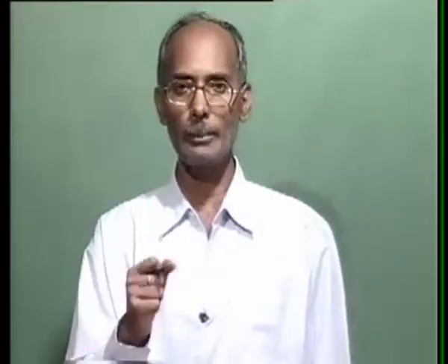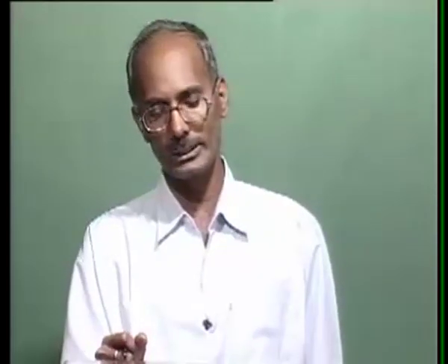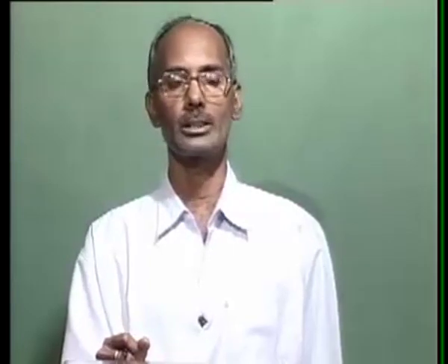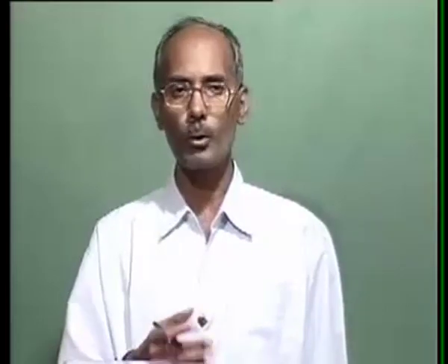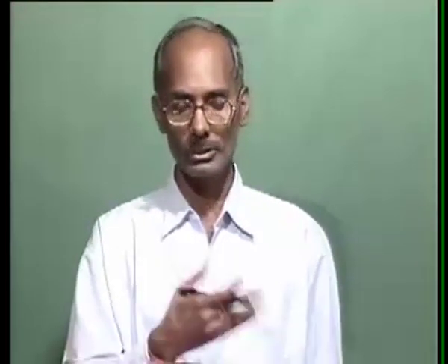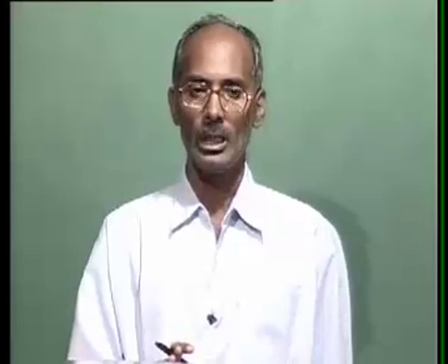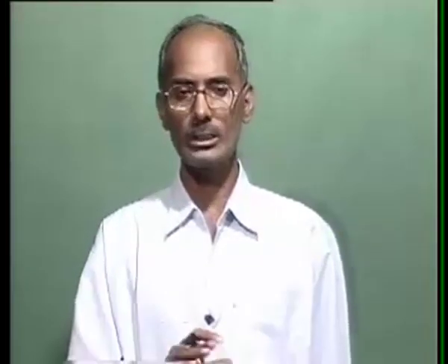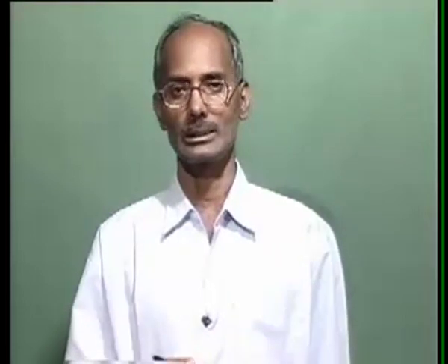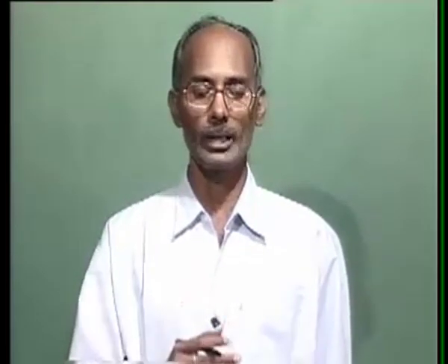So we can see with the help of this fast acting valve, meaning rapid closing and opening of the steam valves, we can again improve the transient stability of the system. So we have seen in this lecture how we can improve the transient stability, and what the various methods are. We can solve the differential equations. First we discussed the various methods, including Euler's method, modified Euler's method, Runge-Kutta methods, and of course the trapezoidal methods, and then we saw the various ways to improve the transient stability. Along with that, we also saw the various factors influencing the transient stability of the system. Thank you.